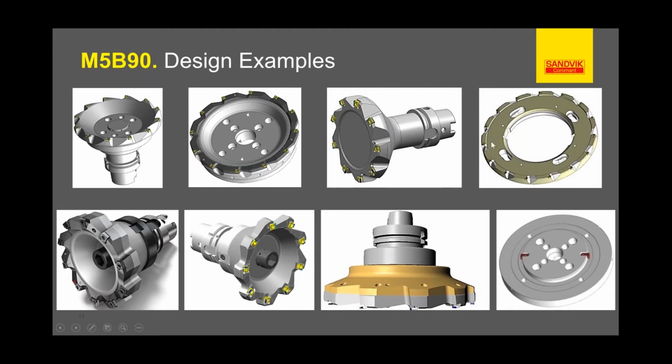We've got ring cutters, like this one over here is a ring cutter, the adapter plate for that. The other thing we're doing, if you go to this left-hand corner over here, this is a 2-piece construction. It's an aluminum body that's anodized with a hard coat, and then a steel ring that holds the inserts with the pockets, so you don't have wear or deformation. That steel ring is actually heated and put on with a shrink fit method, so it's very, very tight, and it's key driven.